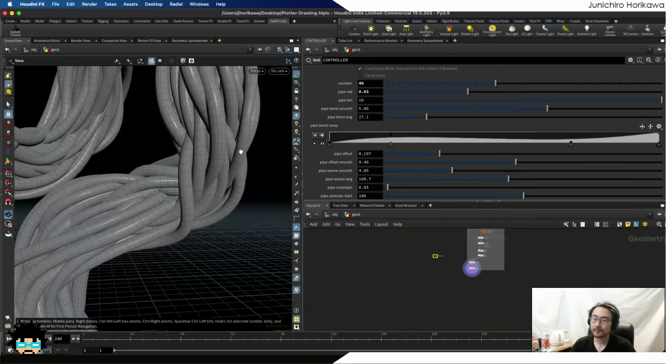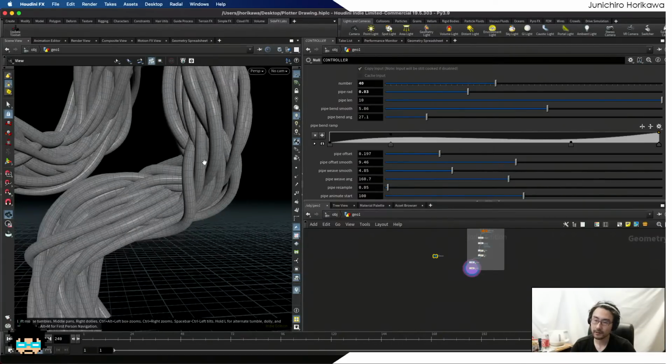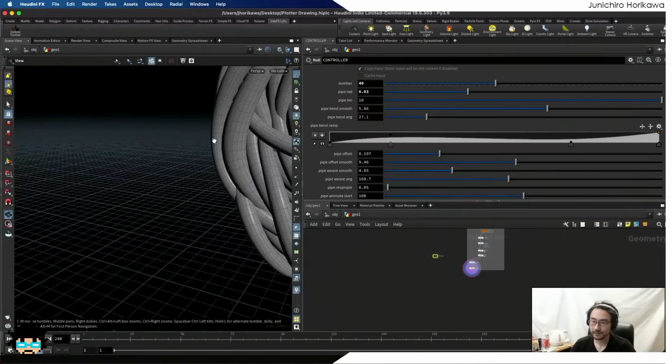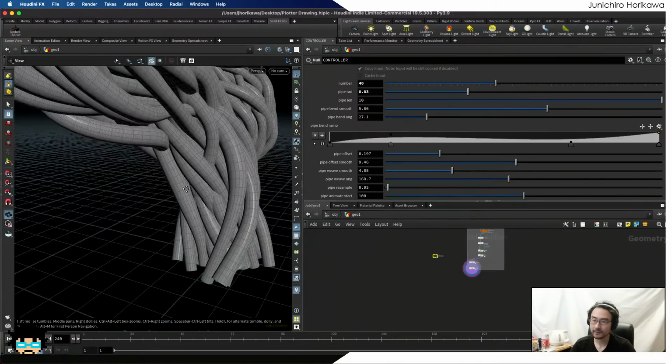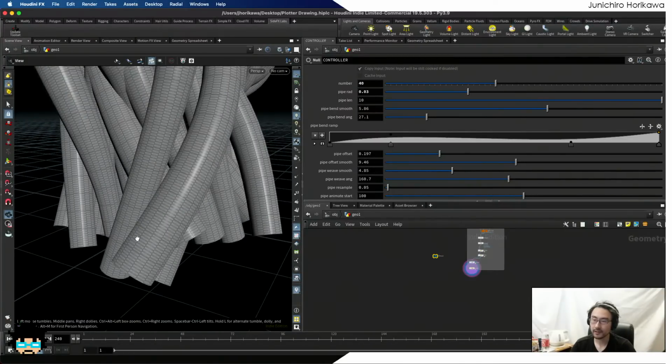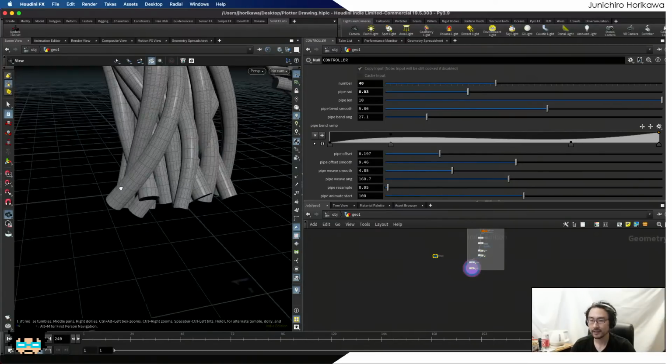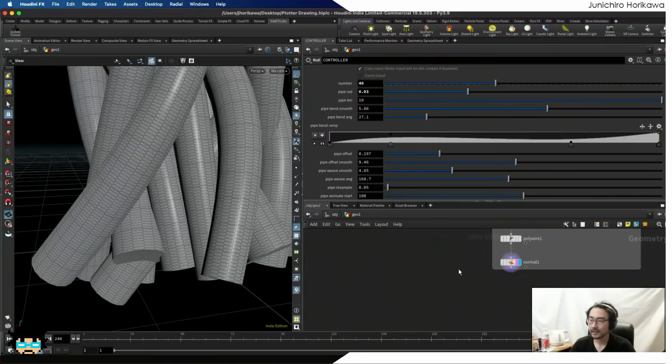But the most used process is to create a contour on top of this geometry. Okay. So what I would like to do is to create contours running in this direction, this pipe running direction. A bunch of contours in this direction wrapping each pipe. Okay, that's what I would like to do. And I guess there are many ways to do that.